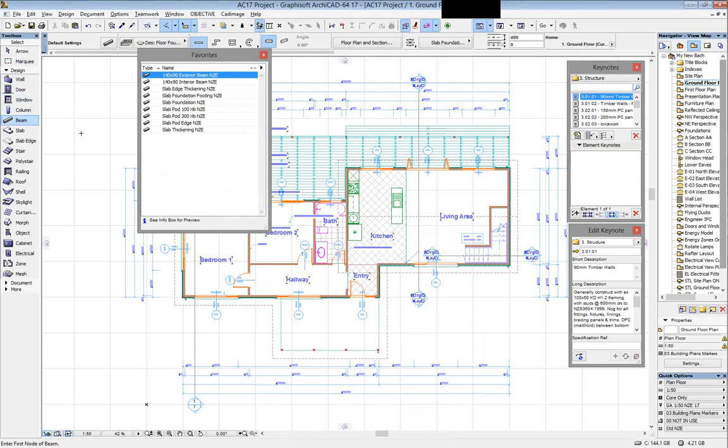But now with the introduction of building materials, we find that the coverings tool relies heavily on objects, and you can't apply building materials to objects. You would never be able to get the floor slab beam cleanup that we did in section CC if you use the CADimage covering, because you can't get building material priorities into objects.